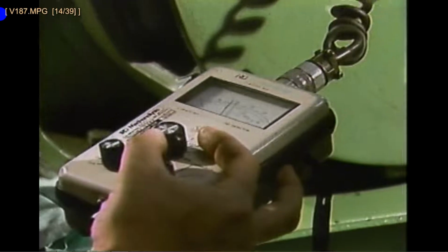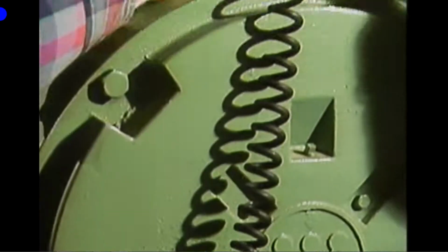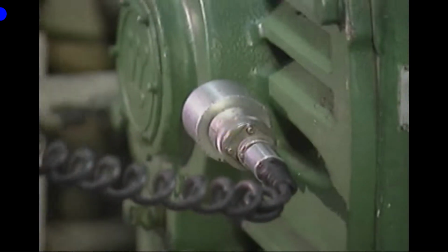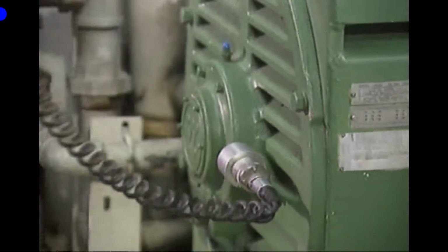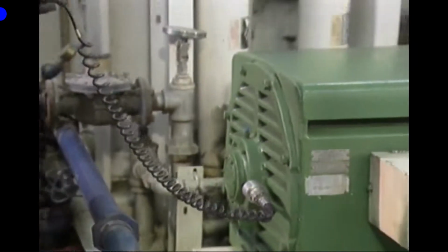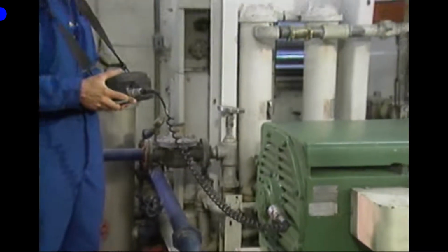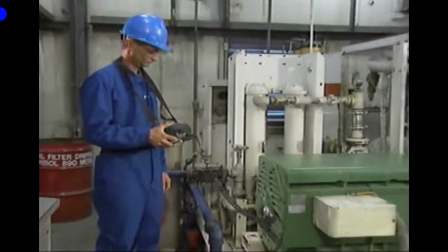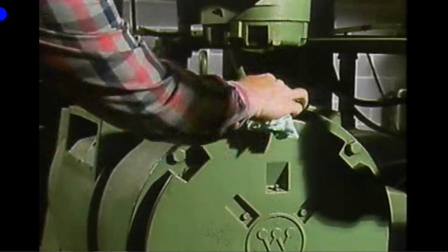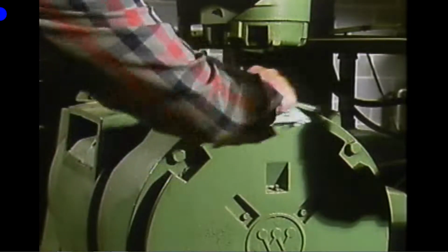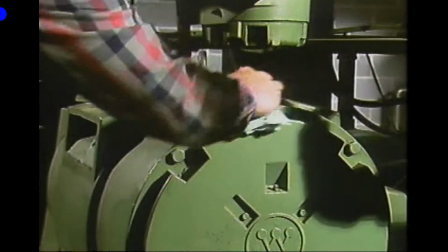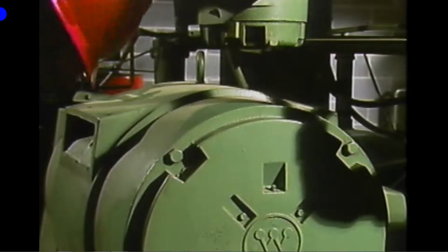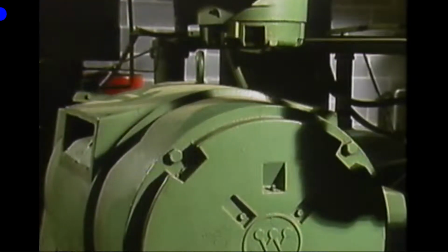When a transducer is used to take vibration measurements, it's either held in position by hand or it's mounted to the equipment. Proper placement of a transducer includes how it is held or mounted to the machine it is monitoring, as well as where the transducer is positioned. For example, the surface a transducer contacts should always be smooth and free of any material that could interfere with the contact between the transducer and the machine.